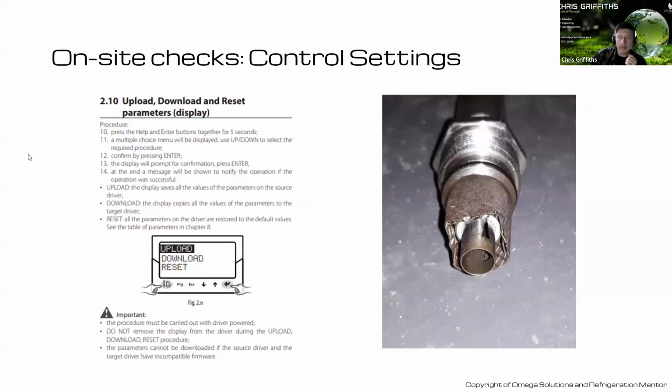So the right-hand picture here is from a flash gas bypass valve, wasn't it, John? Again, very blocked up. Was it the PRV or the high pressure valve? Sorry, I think that was a high pressure valve, that one. It's stainless steel, this one. Wow.